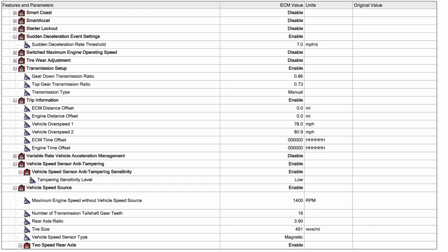Variable rate vehicle acceleration management is another specialty setting. That's best set by the OEM. It'll be with usually an automatic or a special kind of transmission. And it can either be to protect the device that the engine's driving, or it can be to control that particular type of vehicle in a certain situation. Remember, these engines go in all kinds of vehicles that travel over terrain and or highways.